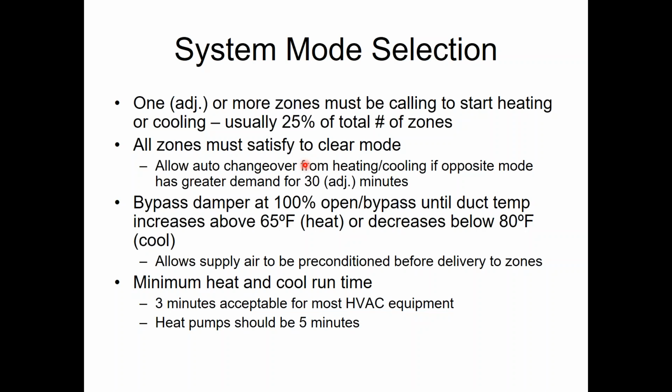I also don't want my cooling to kick on because there's one small zone that serves the copy room or something ridiculous like that, or a thermostat that's next to the coffee pot. I can't have that turning the cooling on and off, hitting limit, off, on, limit, off, on. It'll beat everything up to death. So I got to have some minimum on there.